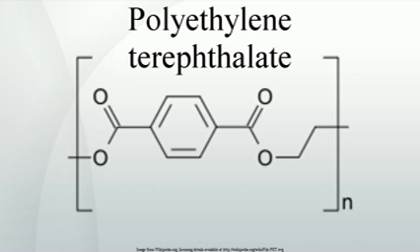Another common modifier is isophthalic acid, replacing some of the 1,4-para-linked terephthalate units. The 1,2 or 1,3 meta linkage produces an angle in the chain, which also disturbs crystallinity. Such copolymers are advantageous for certain molding applications, such as thermoforming, which is used for example to make tray or blister packaging from co-PET film, or amorphous PET sheet, APET, or PETG sheet.